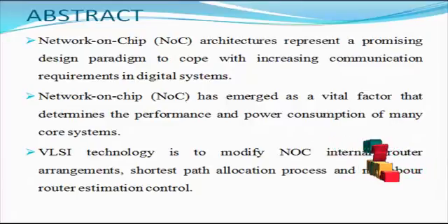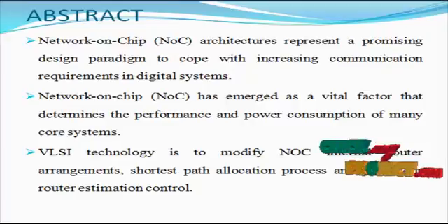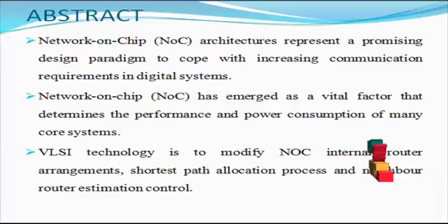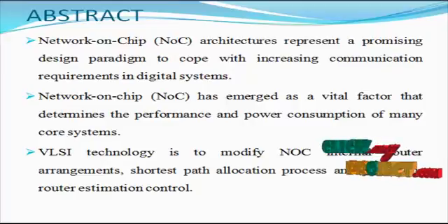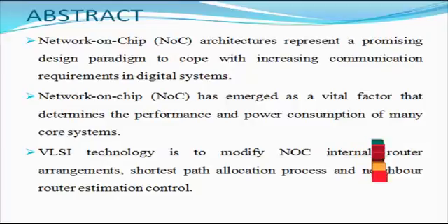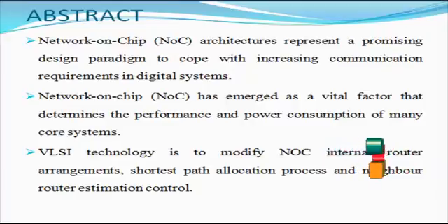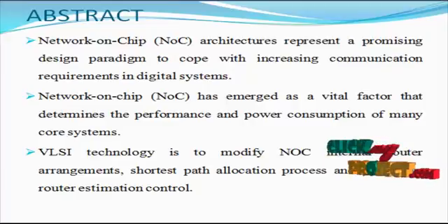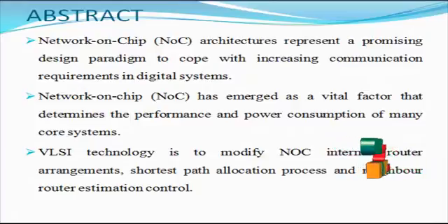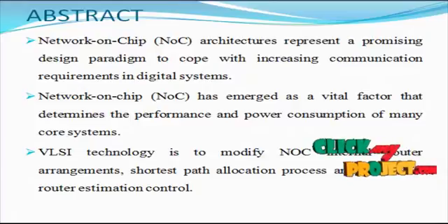3D IC technology drives network on chip design towards a 3D trend and the further development of relevant multi-core systems. However, most recent researchers still focus on the fundamental 3D mesh structure and have no conventional traffic pattern modes in realistic applications. In this paper, we present the complete design framework of a distributed shared memory homogeneous multi-core system based on 3D torus interconnections. A gray code routing mechanism is also proposed to solve the deadlock.